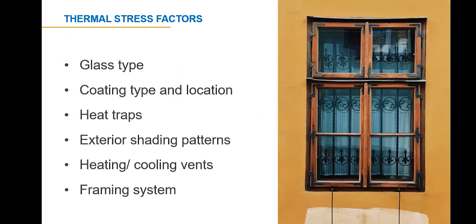The main thermal stress factors are glass type, coating type and location, heat traps, which are blinds, drapes, or drop ceilings, exterior shading, heating and cooling vents, and the framing system.